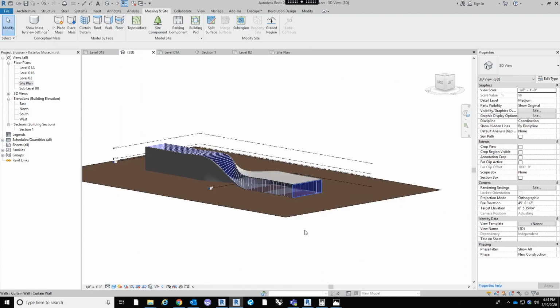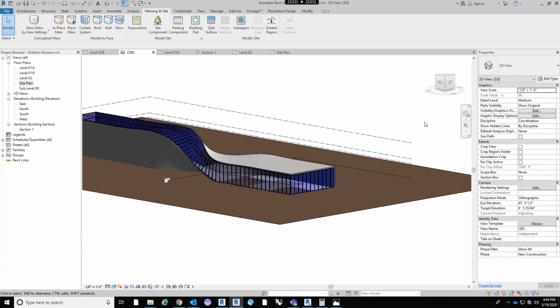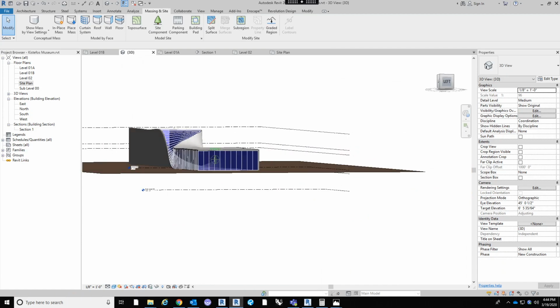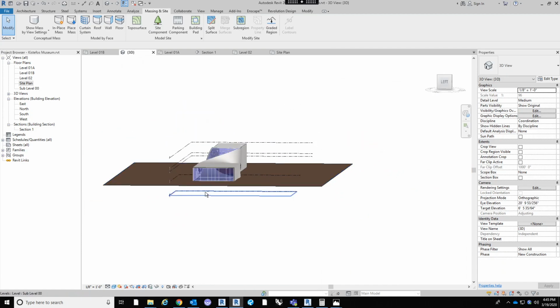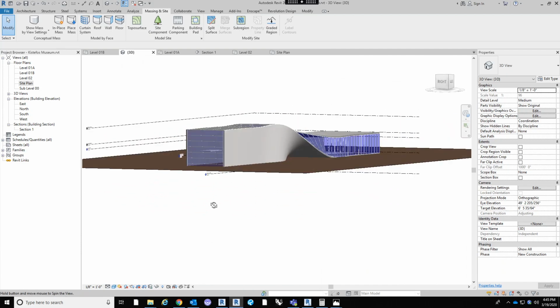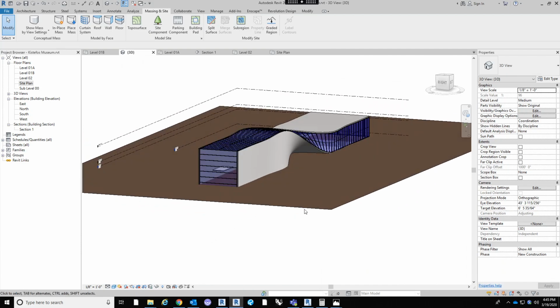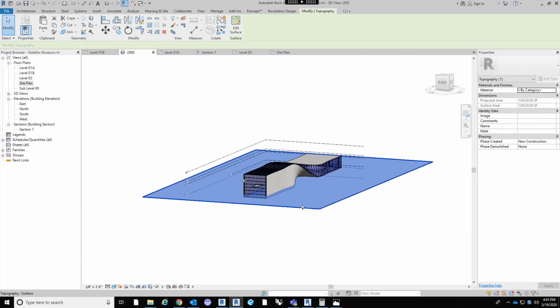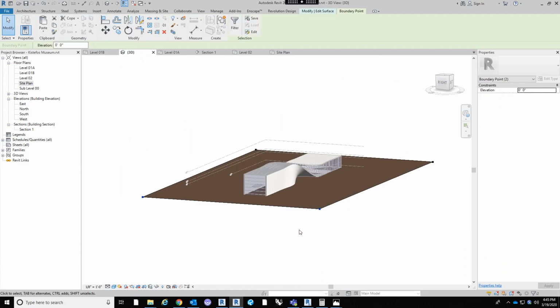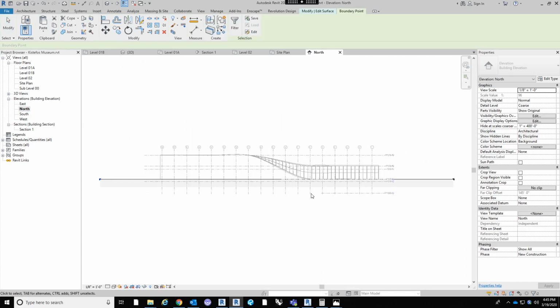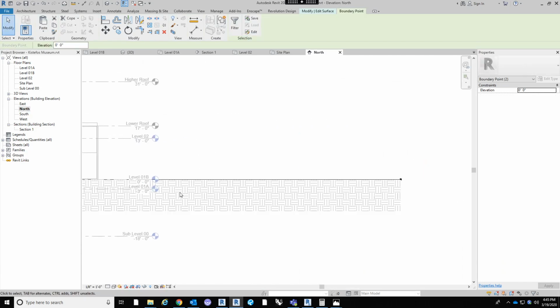All right. That's going to create one flat piece of elevation. If we go to 3D view, you can see it is flush with level 1B, and since level 1A is a little bit lower, it's a little bit higher. So what we'll do is go in to edit surface, and we'll highlight both of the topography over here and do negative, actually what is the difference here? -3 feet.